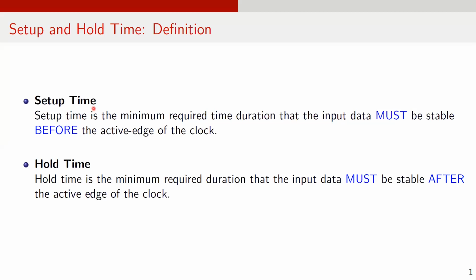First, the setup time. Setup time is the minimum required time duration that the input data must be stable before the active edge of the clock. Or in other words, the input D in the flip-flop must be stable before the active edge of the clock for at least setup time. This is a critical timing requirement in order to avoid possible data contention in the flip-flop.